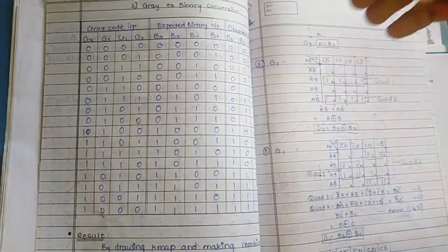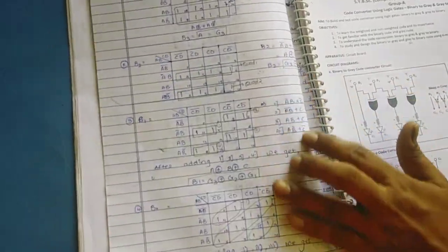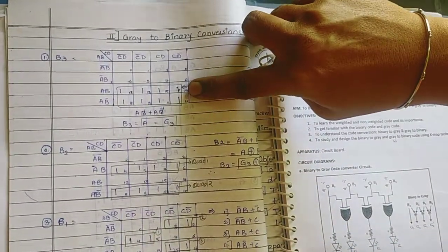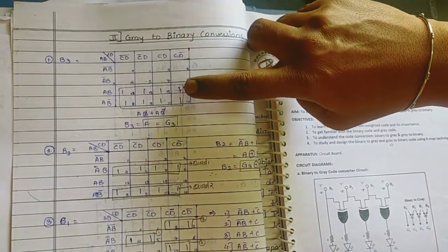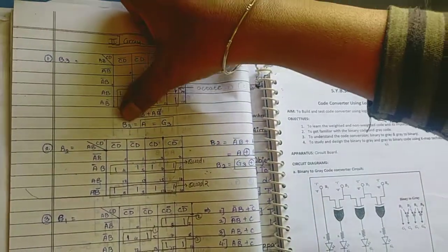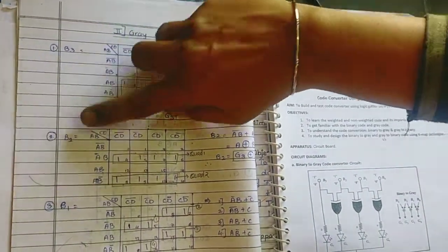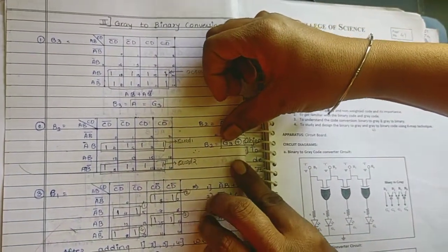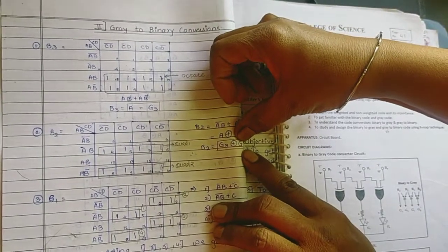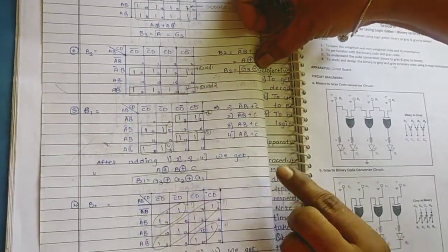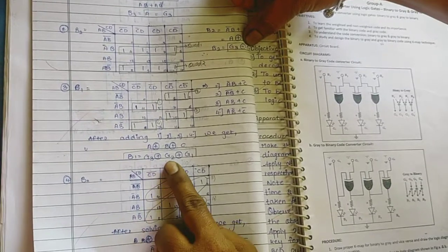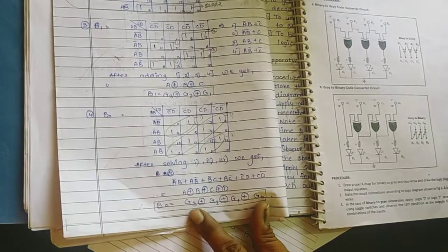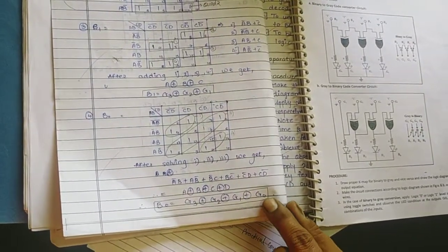After completing this table, we need to draw the K map. After completing the K map, we need to observe whether a pair is generated, a quad is generated, or an octet is generated, and accordingly we will observe here B3 is equal to G3. Then B2 is the mod addition of G3, which is your resultant bit, and then the next bit G2. Similarly, B1 is the mod addition of G3 mod G2 mod G1. Got it, students? And B0 is G3 mod G2 mod G1 mod G0.